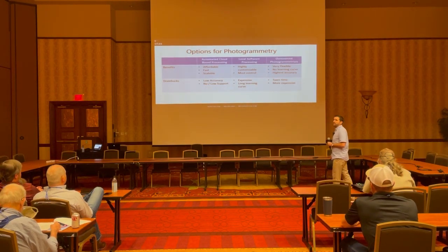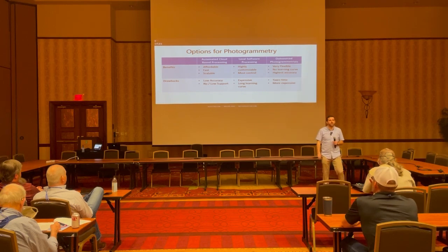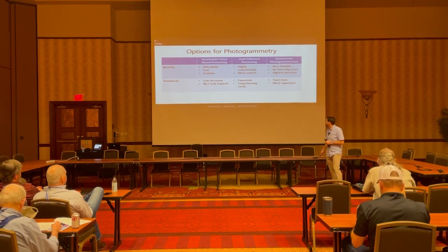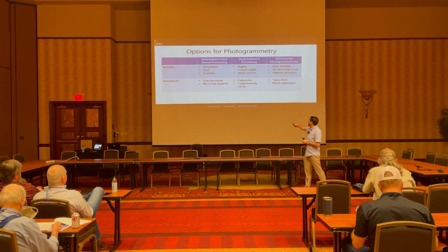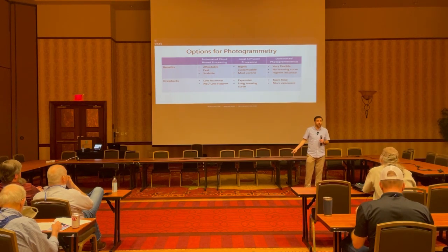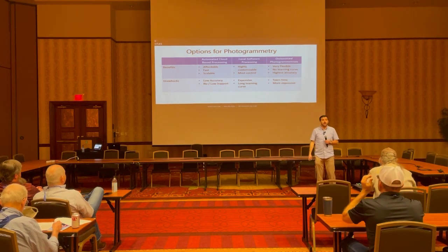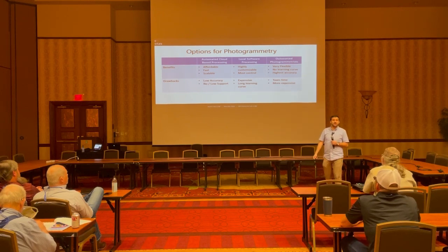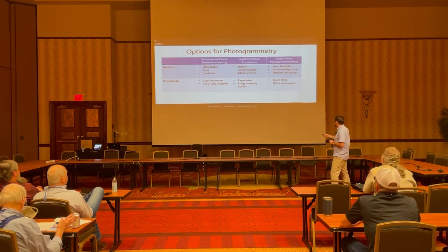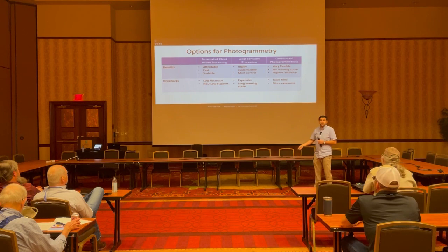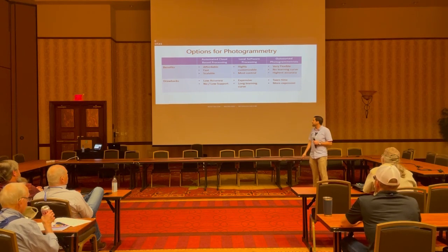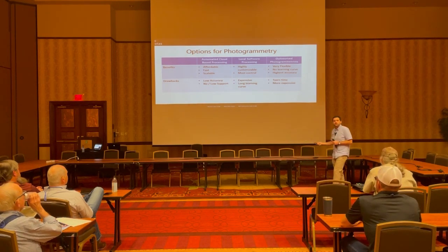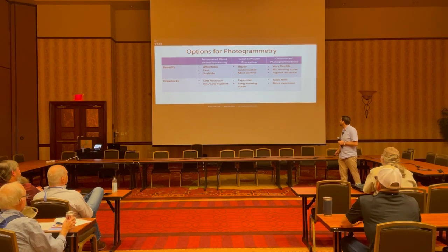There are also different options for how you process your photogrammetry from a business perspective. Number one is your automated cloud-based processing. That's the Drone Deploy thing that I told you about, or any of the other cloud solutions out there. They are typically going to be the most affordable. They are going to be the fastest in terms of their turnaround time and extremely scalable. With the downsides being typically they have low accuracy, which makes it a non-starter for a lot of survey applications, and either no or low support, which is fine depending on what you need.